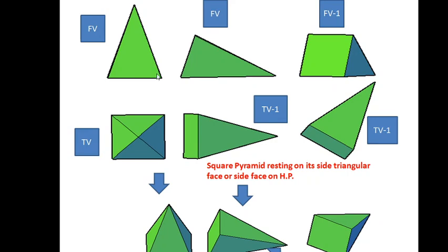So what I have to do is redraw the same front view with respect to this slant edge. I mark this corner, let's suppose, as A dash, and this as O dash. A dash and O dash should be on the horizontal plane, and later on we have to draw the remaining part of the front view. Of course, this is the base. From A dash to D dash distance, in the compass mark one arc, and from the apex to the end point of the base, we mark by the compass.